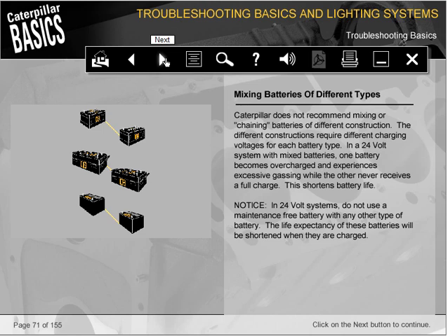Notice, in 24-volt systems, do not use a maintenance-free battery with any other type of battery. The life expectancy of these batteries will be shortened when they are charged.